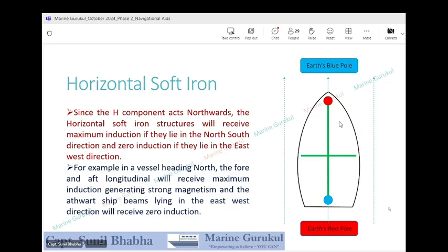After it is brought close to the ship hull where it is ready to be welded, you will first weld it with a single welding seam. You may require further bending of the plate using hydraulic jacks to bring it in complete shape. Then you will be welding longitudinals on top of it, and vertical stiffeners on top of it. So the working upon which is done on a hull plate or a deck or keel plate is much more compared to what is done in a longitudinal.